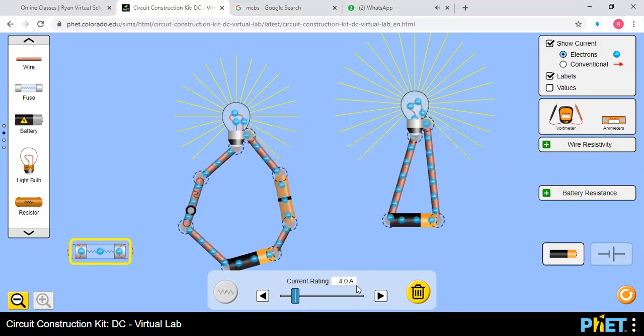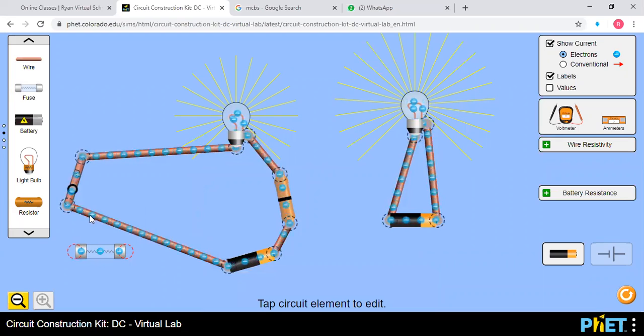Suddenly, if there is 5 ampere or 10 ampere, as you can see during lightning, so many instruments blow up. Current is not always stable. It's always changing. Any small variations, any short circuits, can suddenly increase or reduce the current. Just imagine damaging air conditioners and refrigerators, you know how expensive they are. So to protect all that, we use a fuse. If 4 ampere is mentioned on the fuse and more than 4 ampere passes through, the fuse will blow off.